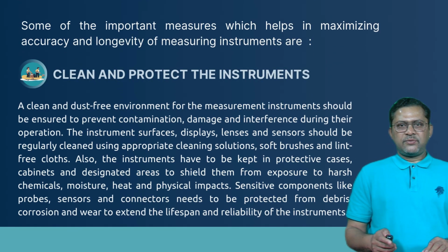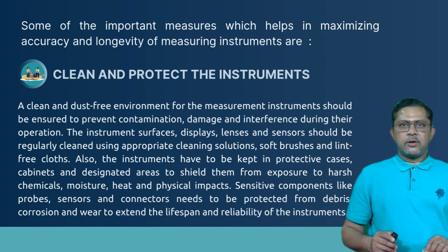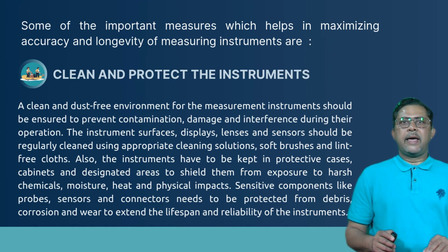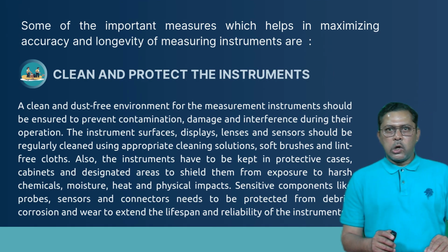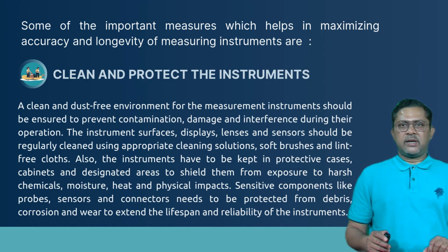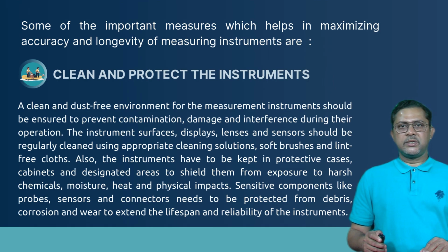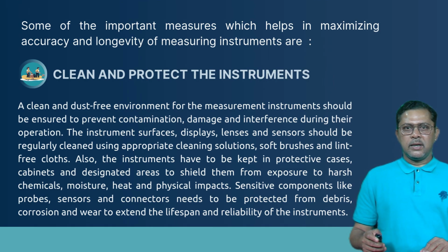A clean and dust-free environment for the measurement instruments should be ensured to prevent contamination, damage, and interference during their operation. The instrument surfaces, displays, lenses, and sensors should be regularly cleaned using appropriate cleaning solutions, soft brushes, and lint-free cloths. Also, the instruments have to be kept in protective cases, cabinets, and designated areas to shield them from exposure to harsh chemicals, moisture, heat, and physical impacts.